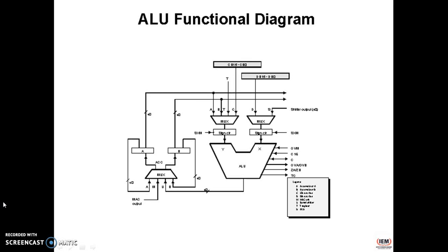Now we are coming to the accumulator. As seen in the figure, accumulator A and B store the output from the ALU or the multiplier or adder block. They can also provide a second input to the ALU. Accumulator A can be input to the multiplier or adder.